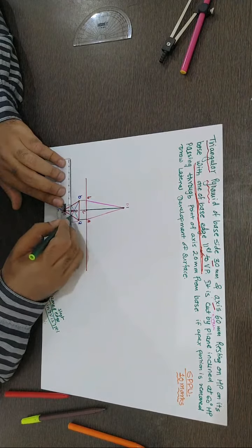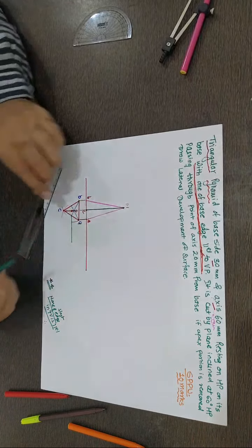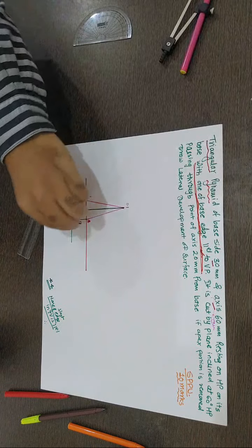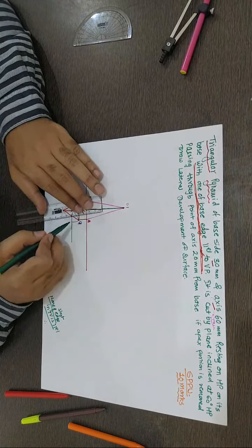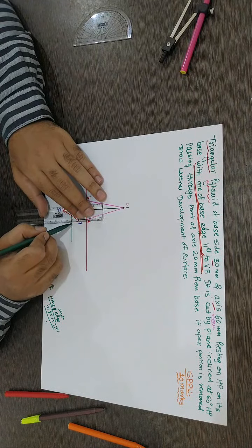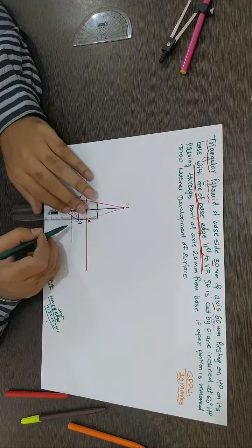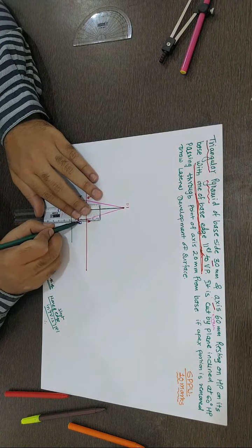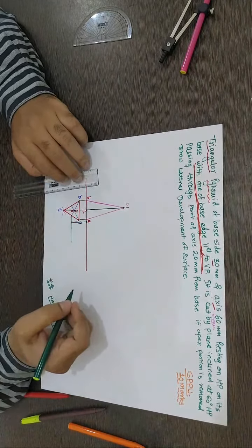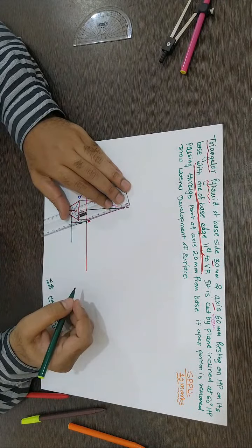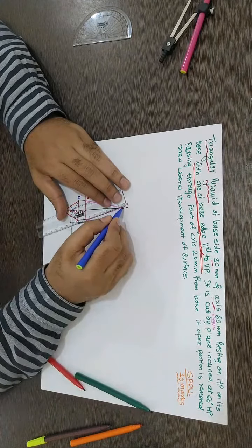So now this intersection, this is horizontal line, making this OA parallel, means this OA, which is now inclined, I have drawn this as straight. Okay, means making this OA parallel. That's it. That's simple technical word you can say. Now extend this point which I have projected here by making OA parallel. Project this point in the front view. This is the true length which you should consider for reference. Now join it with the O.